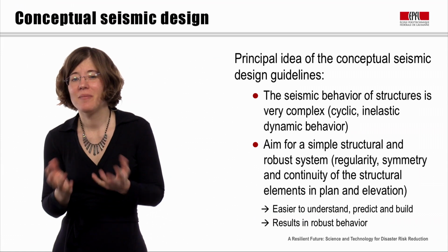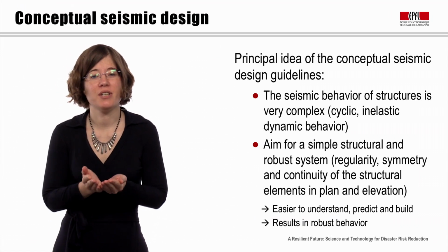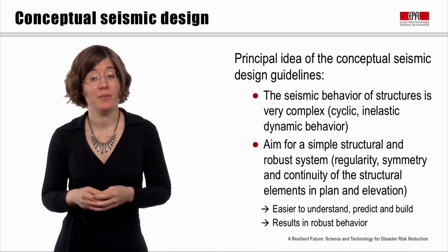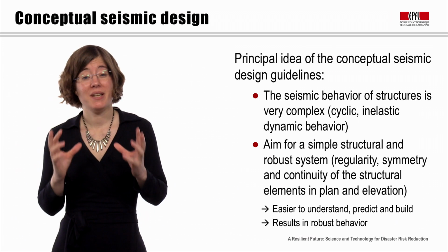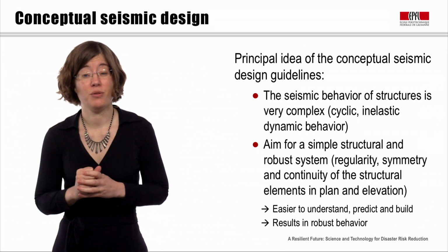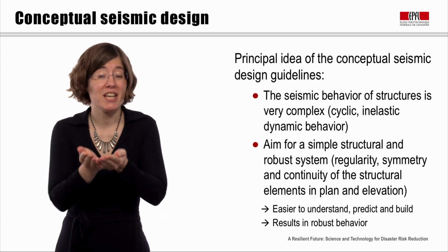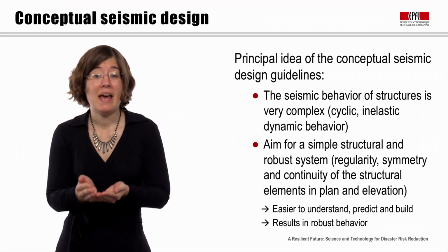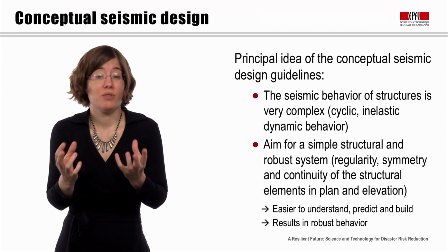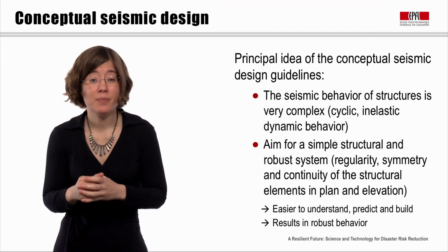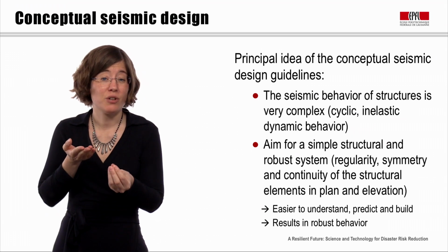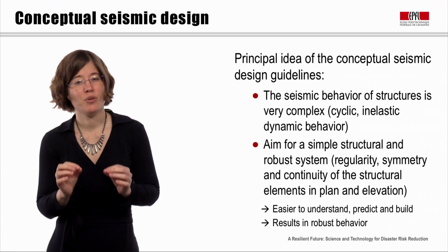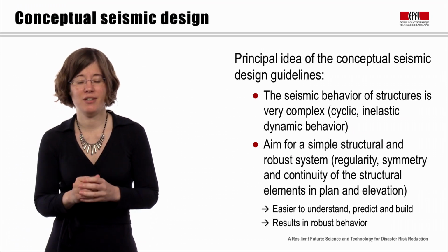That means a system that is relatively regular in plan and elevation, and also a system that has some redundancy. The behavior of a building is really a very complex affair during an earthquake. The building is shaken in all directions, the loading is cyclic, goes back and forth, and during a large seismic event, which drives the seismic design of our buildings, we also expect the buildings to undergo inelastic deformations. Simulating this behavior with computers is today still a very challenging task.